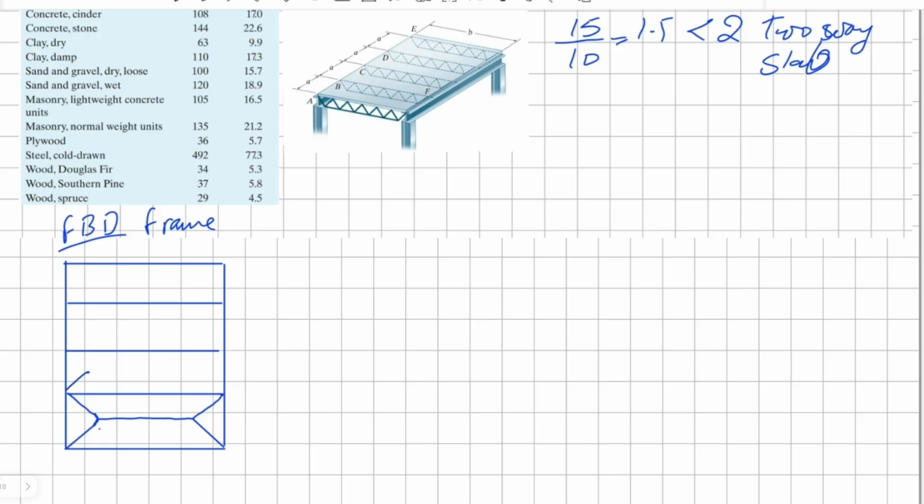And the angle between the corners is 45 degrees. So for example, for this joist BF here, the area shaded in red will be handled by the joist, whereas the area shaded in green will directly be loaded onto the girder and won't affect our joist.